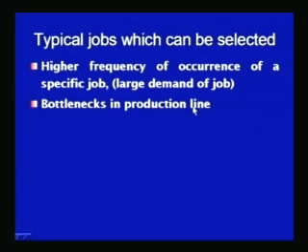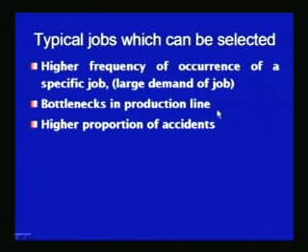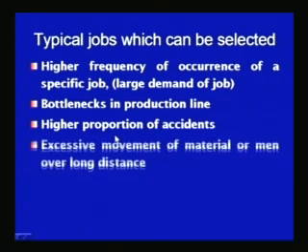A particular station may be the bottleneck in the entire production line, because of which other machines are also underutilized. So, that station can be taken up for method study. A higher proportion of accidents under a certain environment is also a good case for carrying out method study.